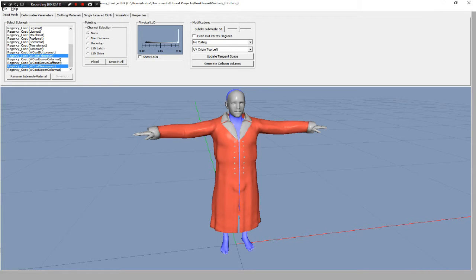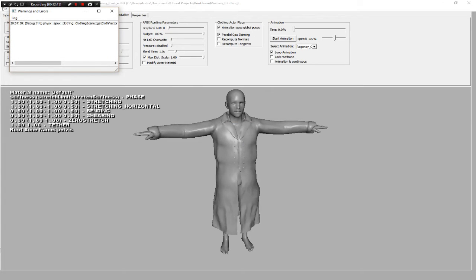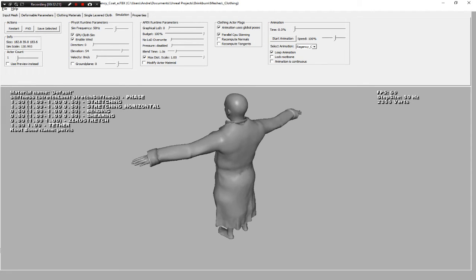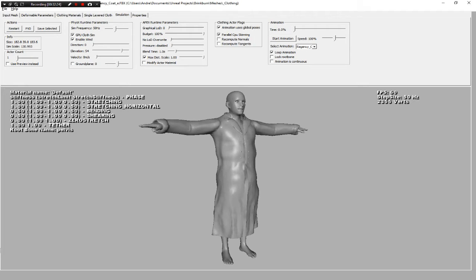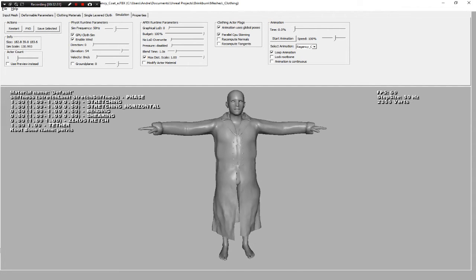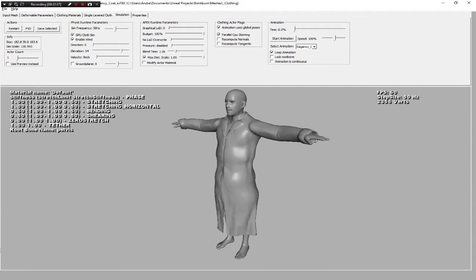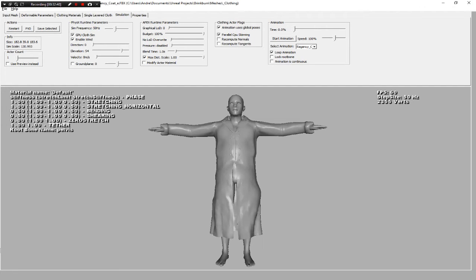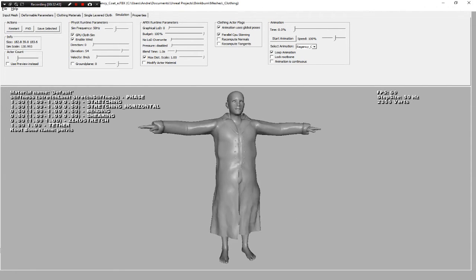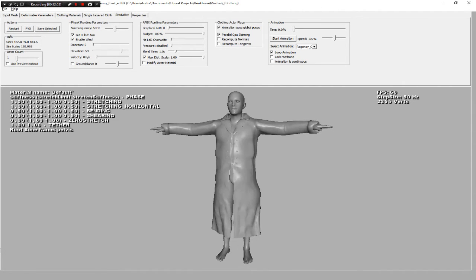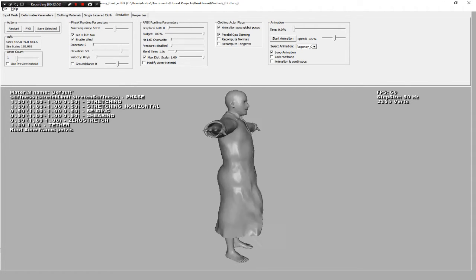But just getting back to this, because this has just been done in front of you. If you do your start simulation, you'll see there's 2,000 verts being calculated. This is a bit much. You want it to be less than this. But if your frames per second here are okay, assuming you have a good computer that is able to calculate this stuff easily, if you have 60 frames per second, it means the performance is not too bad. But again, you really want this to be less, maybe 1,000, maybe even less. The fewer vertices you have with a good working model, the more performance you're going to have.